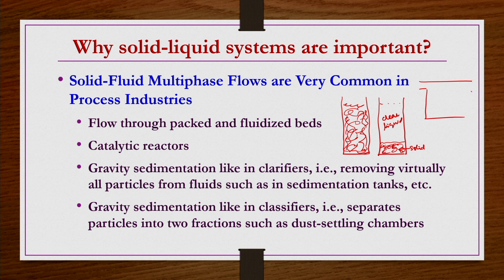So we have a container like this, right? From here the dust laden or particle laden air comes in like this. These particles have different size distributions, let us say. Whatever particles have the bigger size will have the higher settling rate, so they will be settling at the front part of this chamber, while the gas or air which is carrying particles is flowing inside.